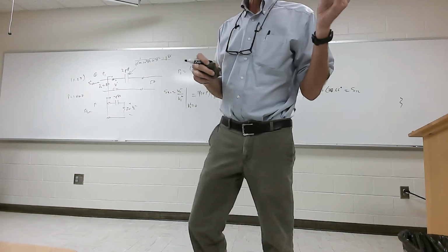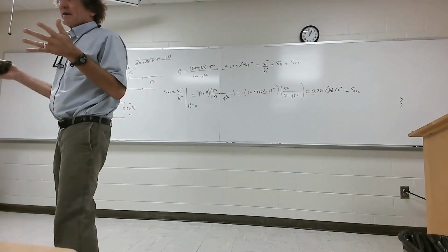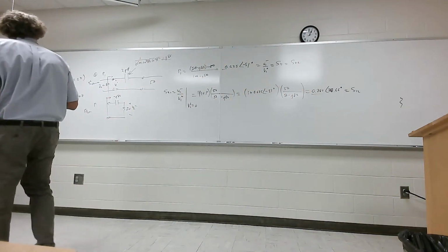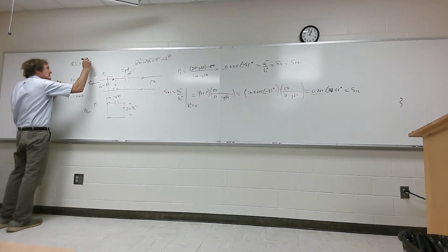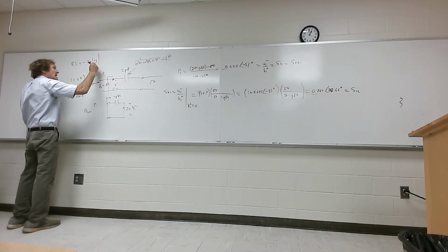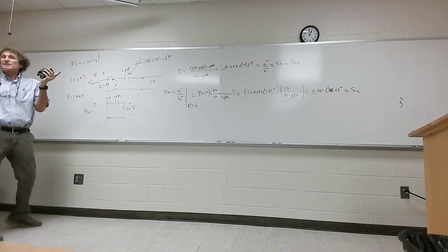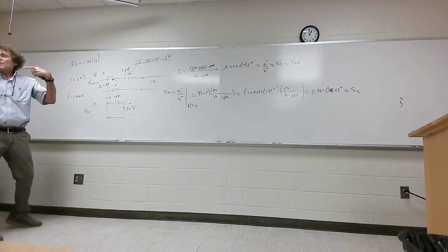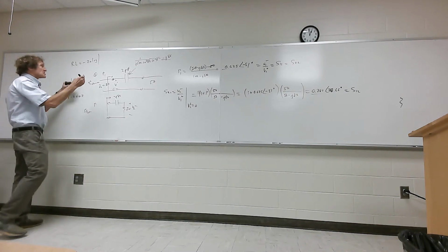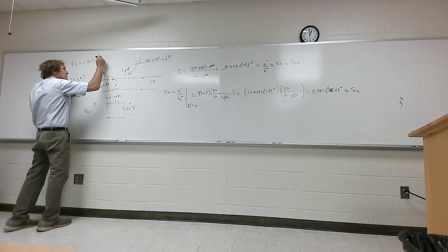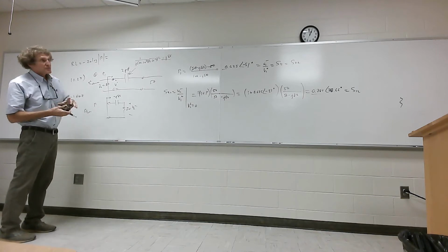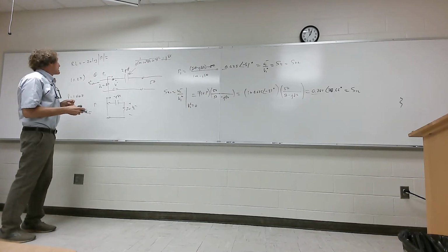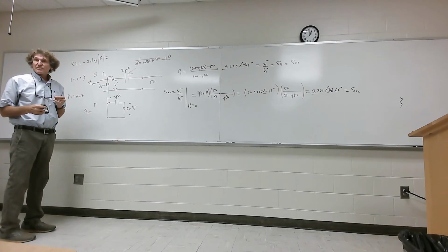All right, then what do they ask for after that? Return loss, insertion loss. Right, you can forget about the angle, just take the magnitude. So what is return loss? It's minus 20 times log, base 10 log, of the magnitude of the reflection coefficient, S11, correct? Because there is no ricochet coming out of port 2. So it's just the magnitude of the reflection coefficient. Return loss, either way, is going to be the same. What is that? Take the magnitude 0.625, take the log of that, and put minus 20 in front of it: 4.08 decibels.